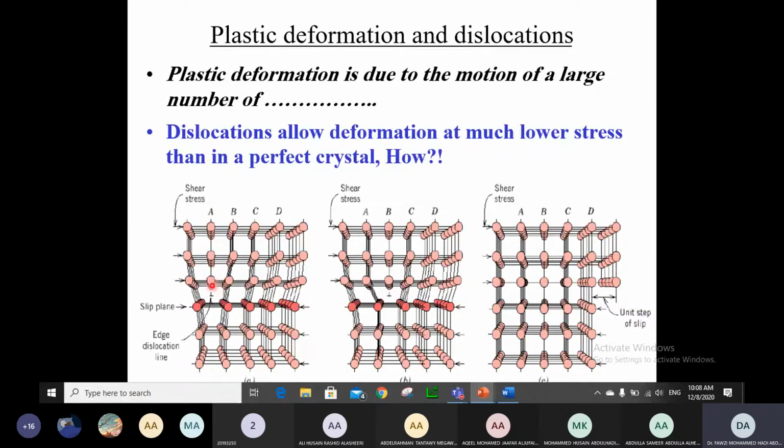When it is pushed in, it causes internal stresses in the vicinity of the dislocation, as you can see here. We mentioned that in the last lecture. Since this is like a self-interstitial defect, not a vacancy, it causes a compressive load here and a compressive load there.